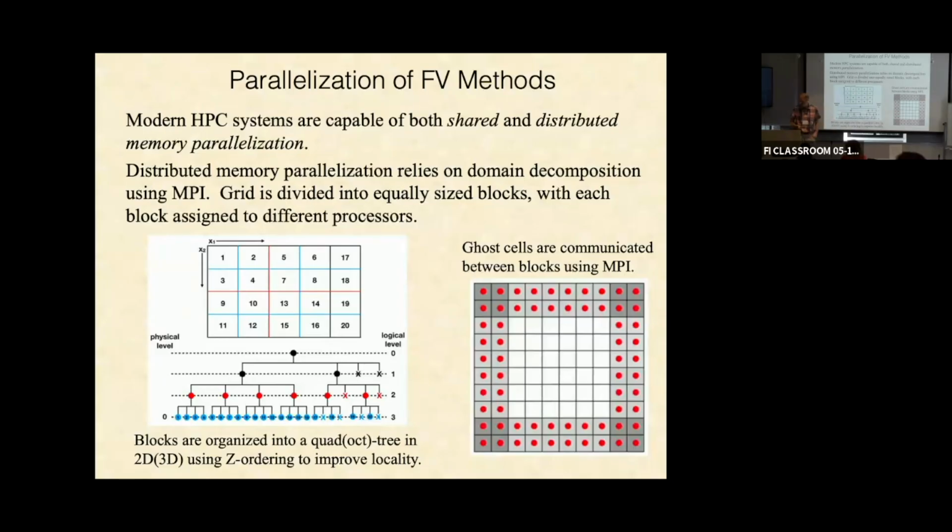Great question. Yeah, naive big picture question, but with the ghost cells being sort of the mechanism that you're using to set your boundary conditions, would you not achieve the same thing by just controlling the outer edge of the active cell? Why put a whole another cell there and worry about its center instead of, for example, just controlling the flux on the outer edge? You could impose the boundary condition through fluxes. You're right. You can impose boundary conditions on the fluxes.